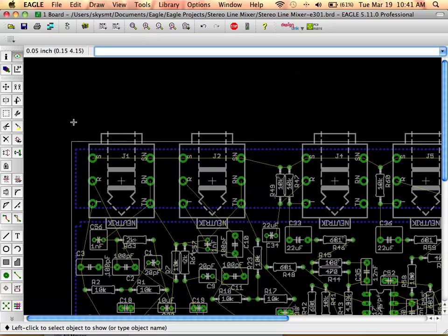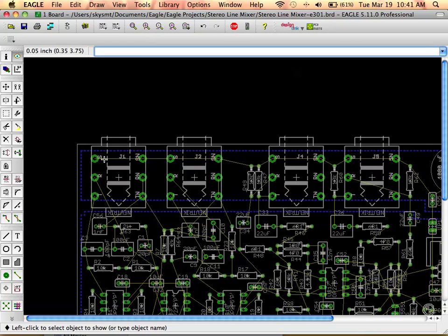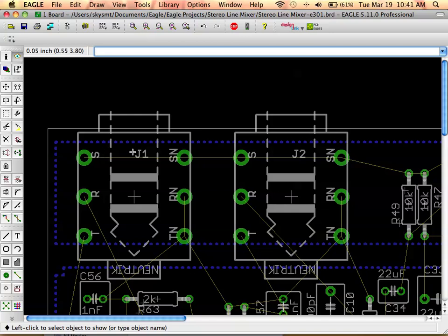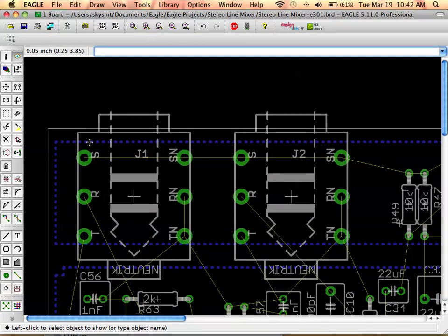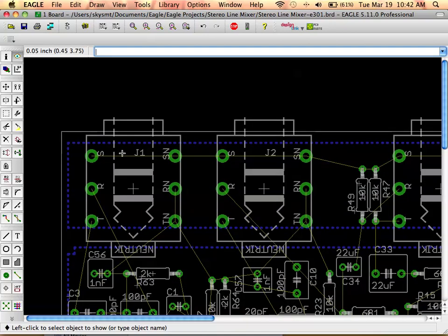Okay, and through various methods, 60 hertz noise can travel on the ground conductor, on the sleeve of your interfacing cables. And the thing to do is to recognize that it's going to be there. It's unavoidable, certainly for longer cable lengths.